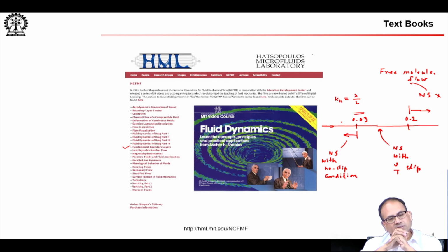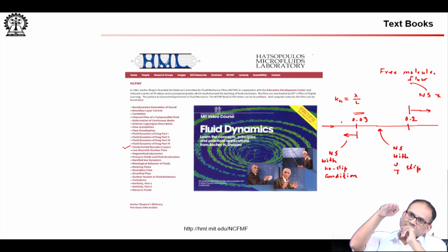In aircraft performance, you learn about expressions such as the service ceiling of an aircraft and the absolute ceiling of an aircraft. It is not exactly in the jurisdiction of aerodynamics, at least in terms of curriculum, but nonetheless, your rate of climb. So, the absolute ceiling is when you do not have excess power.